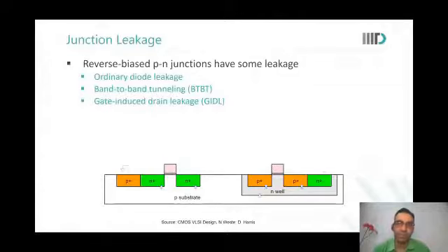Sir, Vaishnav? For all NMOS, sir, I understood that there is a common P substrate. That's the reason why we are grounding all the bodies to ground. But sir, why is Cadence giving us an option to connect the body somewhere for an NMOS, to be specific? I do understand that for PMOS we have that, but for NMOS, why does Cadence even give an option? Why can't it directly ground all the bodies of NMOS?